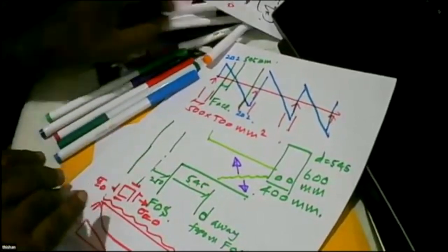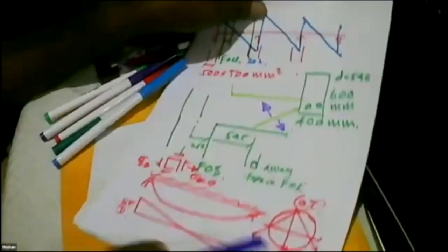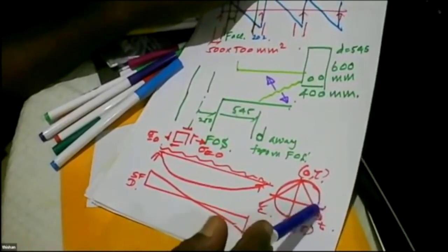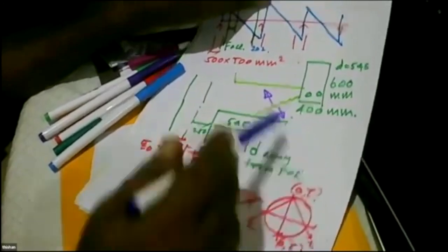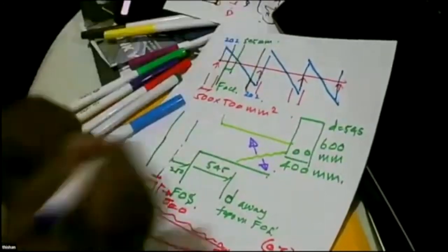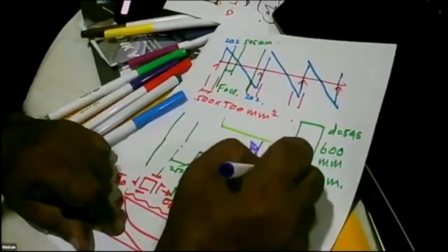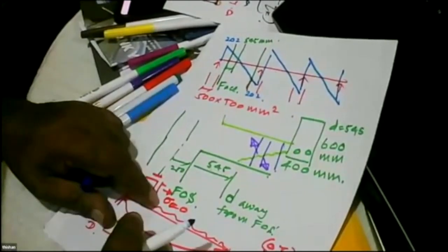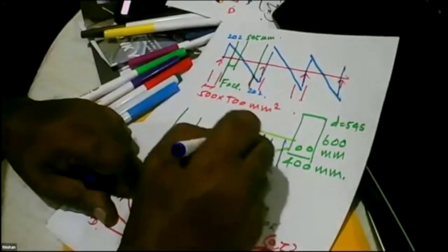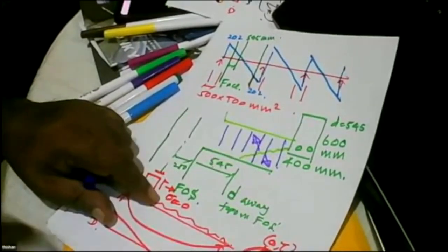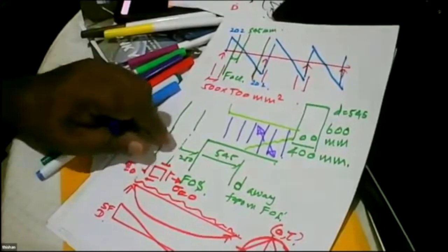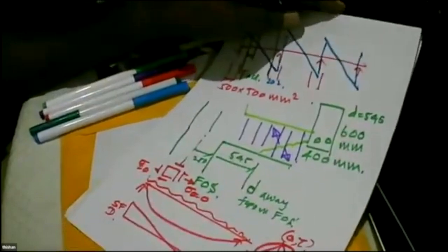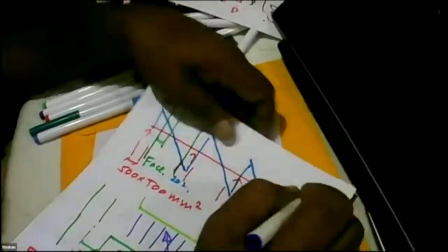So shear failure is a tensile failure, because this maximum stress that you get in the Mohr circle will cause the shear failure, and it's a tensile failure. So it's tension. So how to prevent this? Links like this. Tension is taken by whom now? Tension is taken by the links. So we provide links, and shear failure can be prevented. Shear failure is a tensile failure, and tensile failure means we have to prevent it by using vertical reinforcement.